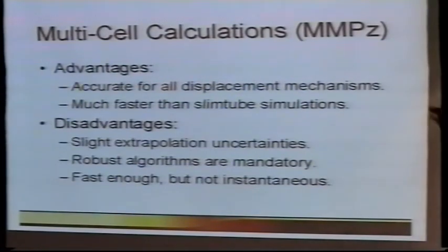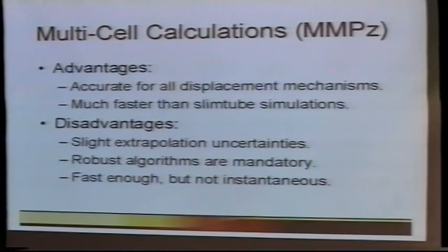We get the right answer only if we use an infinite number of cells. But we can never use an infinite number. So this calculation method might use a finite number, 50, 100, 200. I've seen one case where I had to go up to as high as about 500.